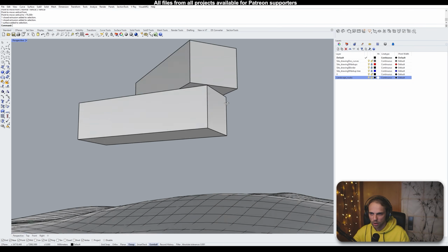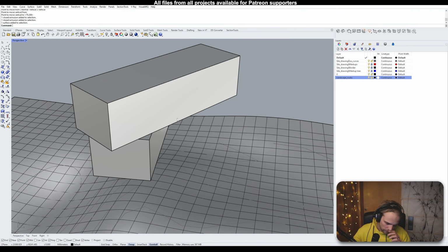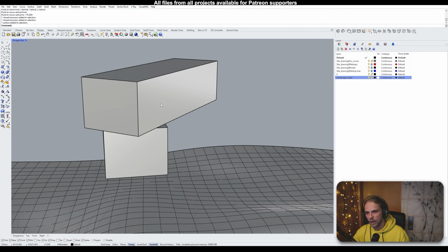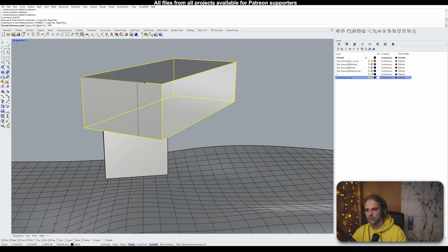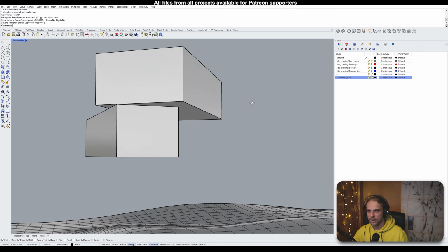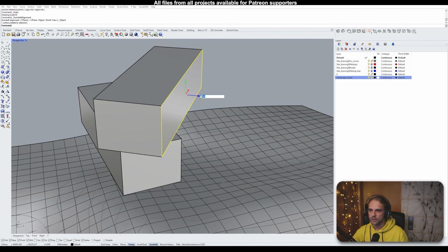Okay, now I'm going to make it a little bit wider in the top, and also I'll make the overlap a little bit bigger. So the first thing, wider. I could just start doing scale 1D like that from here to here and specify 7,000, right? And just click, and now it's wider. Or I can right click on the gumball menu here, choose align to object, Control Shift click on the face, and then just drag out the face as much as I want. 2 meters.